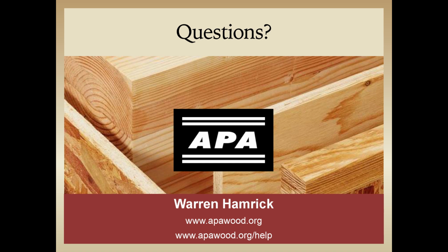Yeah, the spacing of the studs can impact the types of cladding, and that is a really good advantage of having wood structural panel wall sheathing. It can be used as a nail base. So a lot of vinyl sidings require a minimum 16-inch fastening, and the building code does recognize plywood and OSB as a standalone nail base, as we covered. You do need to check, depending on the type of fasteners you're using. If you're using ring shank fasteners, you don't have to do a conversion. It will perform at 16-inch on center spacing.